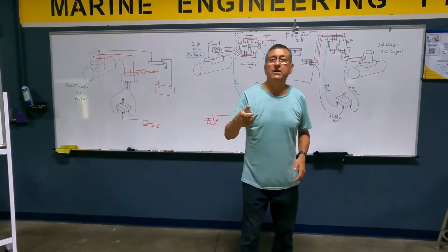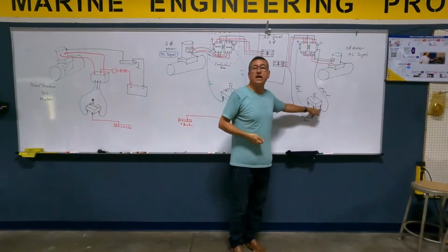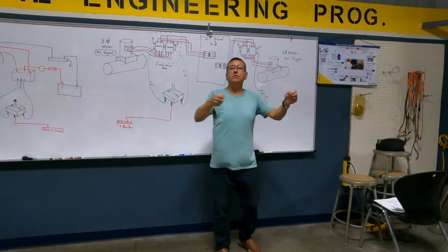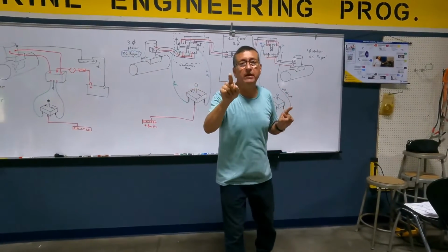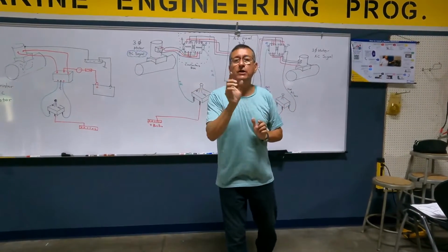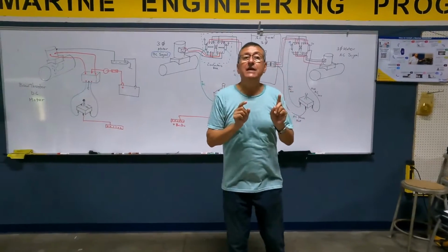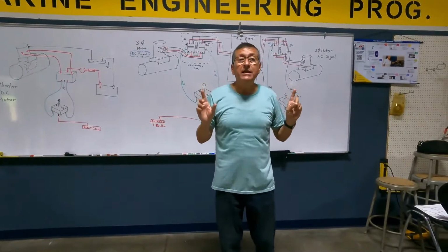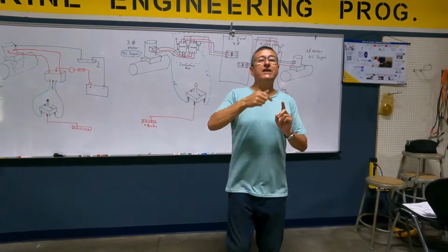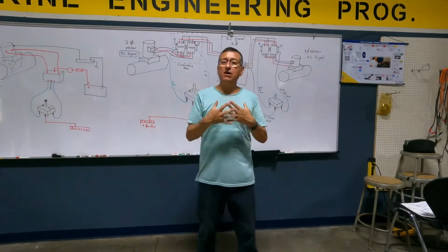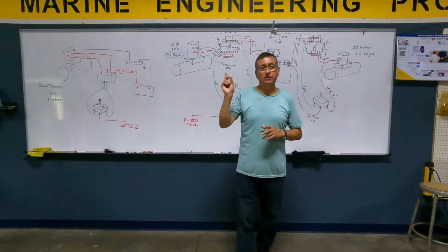Yeah, that's right, the tracer. I put the generator tones on this end, and I go beep. Okay, my cable is good. Or you can use the time domain reflectometer. This is the point where I love to use the time domain reflectometer, because that one says the cable is open 10 feet from here. That's good.